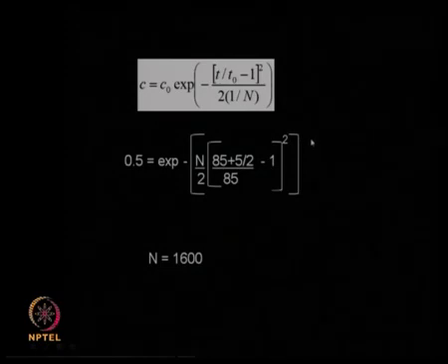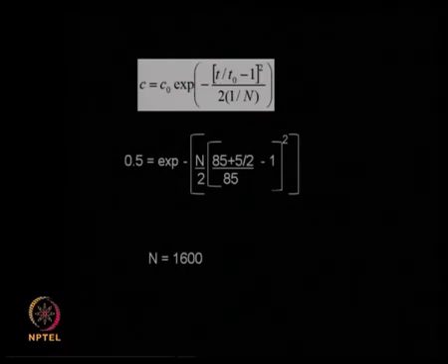So making use of that relation, we can do several calculations, and also by making use of the discrete stage analysis we are able to develop, just based on mass balance, a relationship between the solute concentration going in and the solute concentration going out, and equate it to the accumulation.